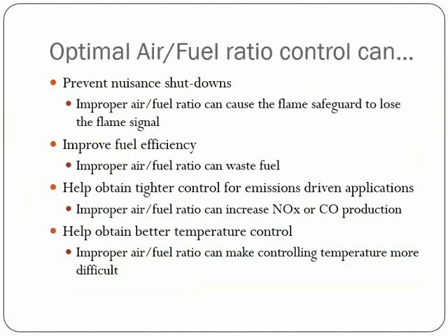If your air-fuel ratio control goes one way or the other, it could still stay within the limits of flammability, but if it's running a little too rich or too lean for its design purpose, you could use additional fuel to either maintain temperature in the chamber or the temperature that you're trying to impart on your product. So having optimal air-fuel ratio will help significantly with your fuel efficiency.